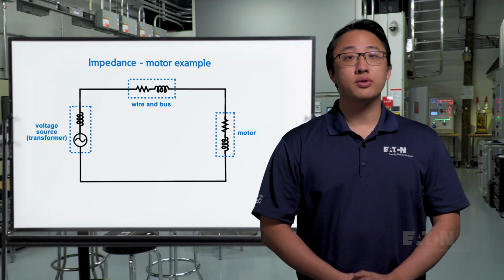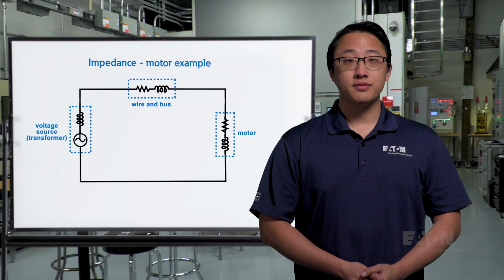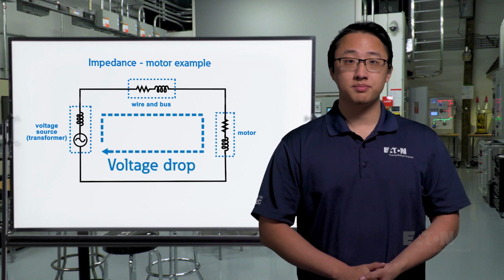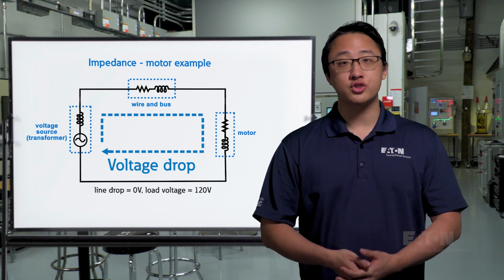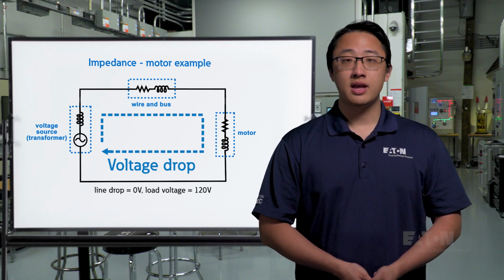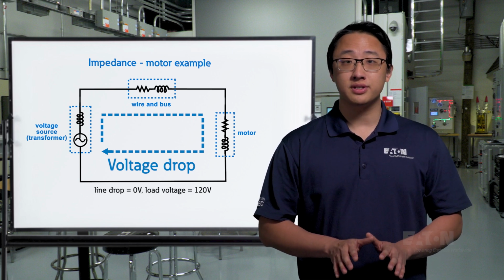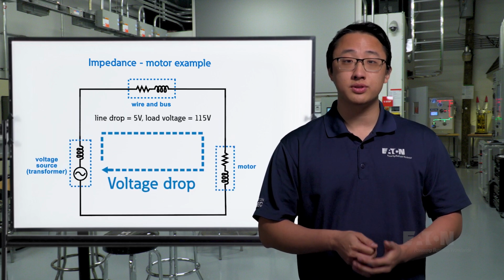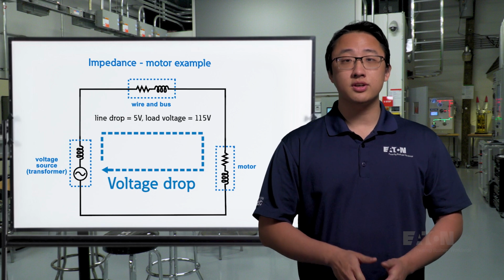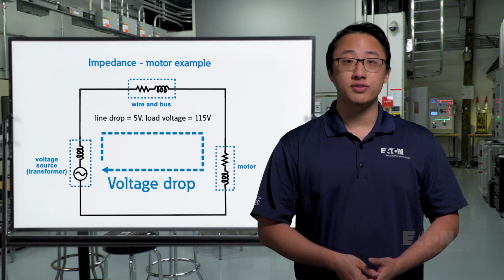With this model, there are several things we can begin to look at. For starters, we can estimate voltage drops. In the simple model, we assumed ideal conductors, that there'd be no voltage drop at all from source to load. However, this is very unrealistic, and oftentimes, long cable runs will result in large voltage drops due to line impedance. In some cases, a voltage regulator may be needed to ensure device performance.